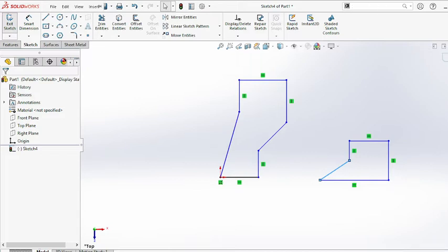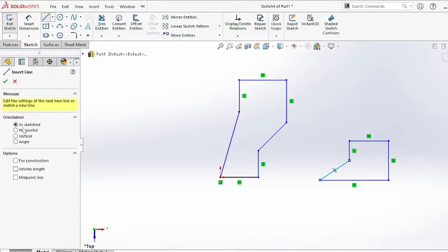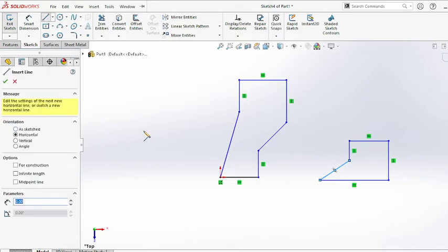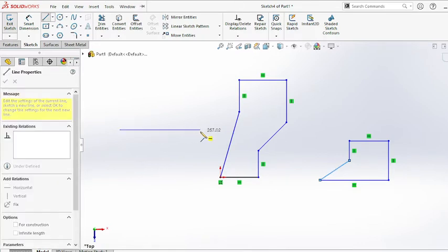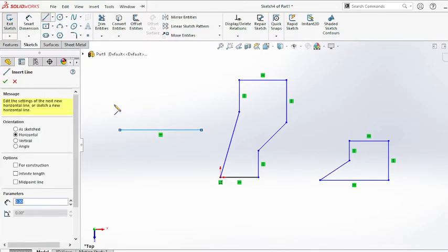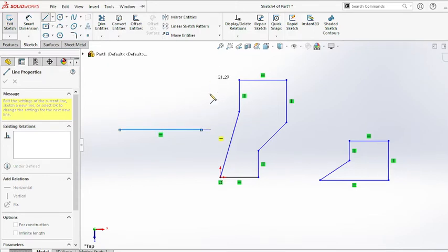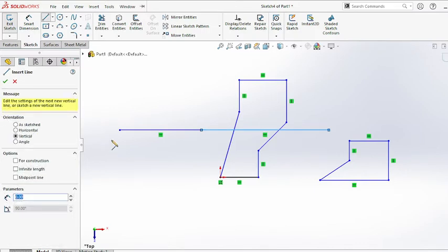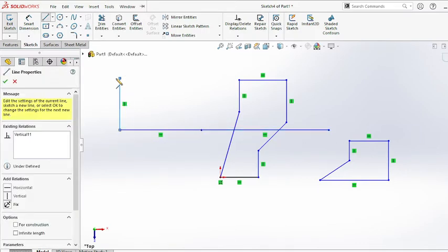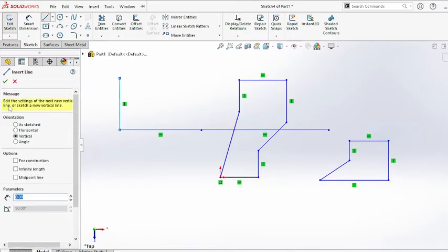See, for example, you can take line command. See, I want to take horizontal option. See, you can draw horizontal line only, always. After completion, see, click on OK. Again, you can click here. I want vertical line. See, it is not possible to draw vertical line. Always draw horizontal only. Clear? So I want one more vertical line. That time, again you have to take vertical, na? That is a time taking process, na? Yes or no? You want some inclined line. Again you have to take angle.